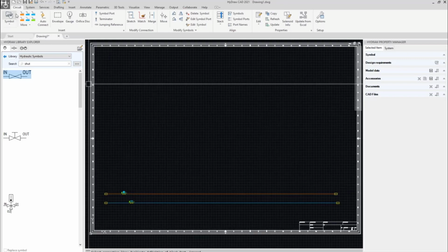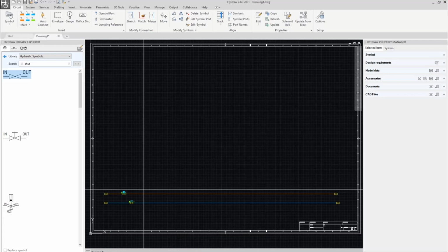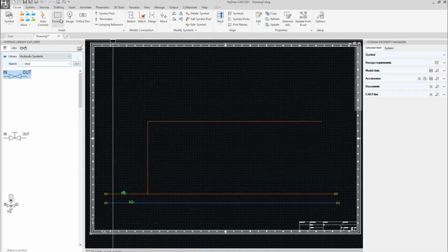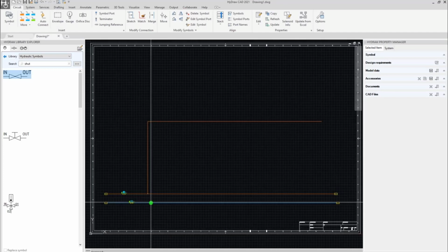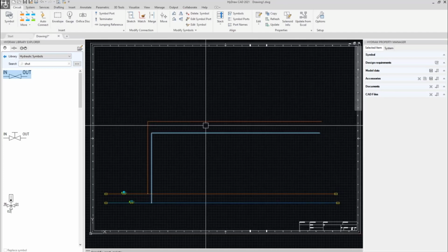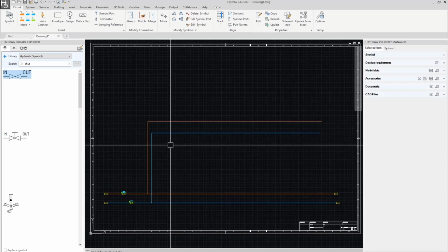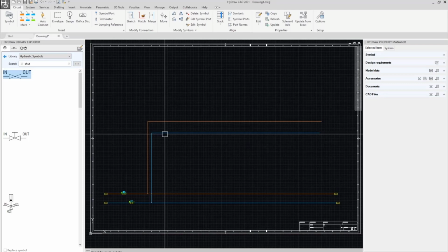Usually we have a pressure line. So we start with a pressure line connected to the pressure line, and let's position it here. And then we make a tank line here. Now we start placing our valves. In this case we will put sandwich mounted valves. Usually valve stands have different sizes of industrial valves. So we can have NG25, NG32, NG6, NG10. So we will do a small mix of these in this application.